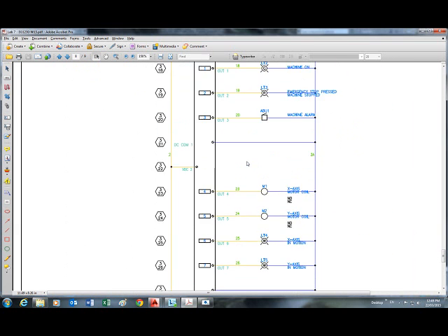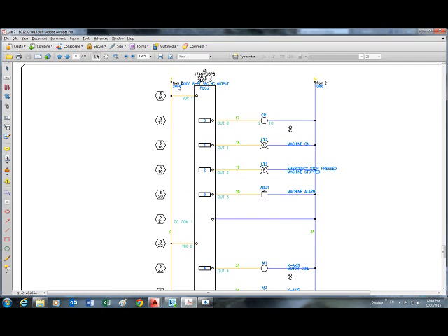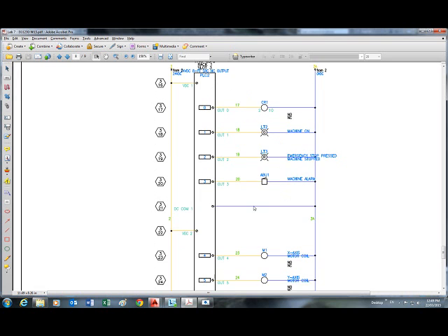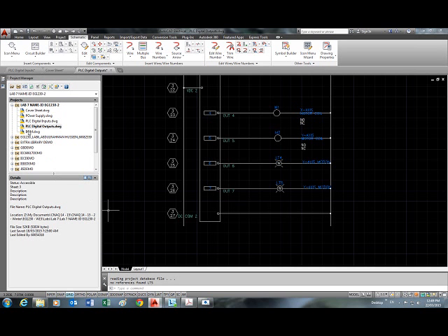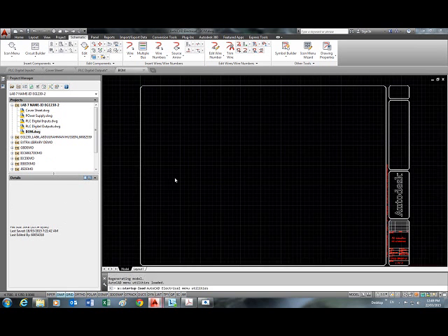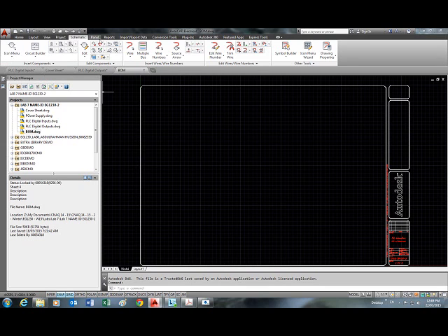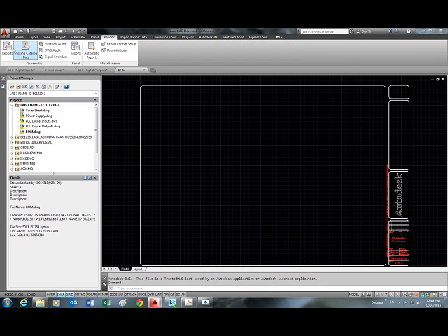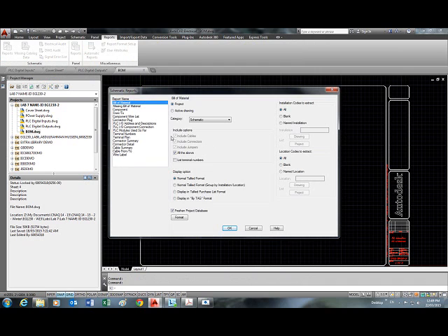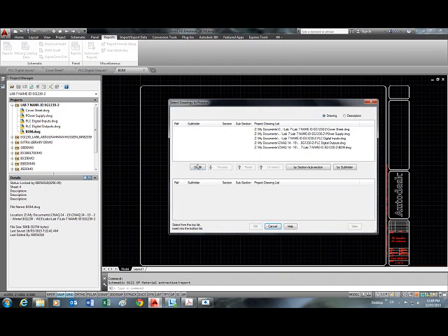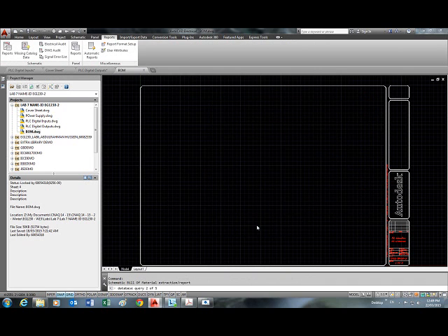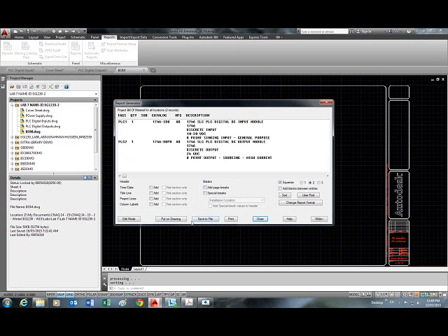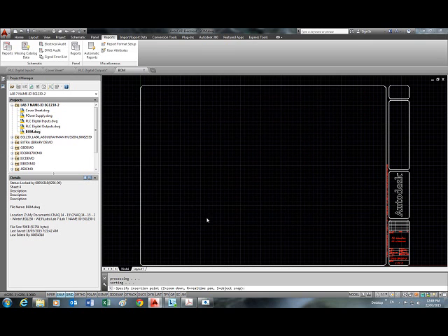And that is pretty much for the output module. So everything is okay, except of course the wire types and the source and destinations. We can do this also partially because there are some components that we have not yet defined in the first drawing. So again, we go reports, bill of materials, okay, do all, okay, put on drawing, okay,